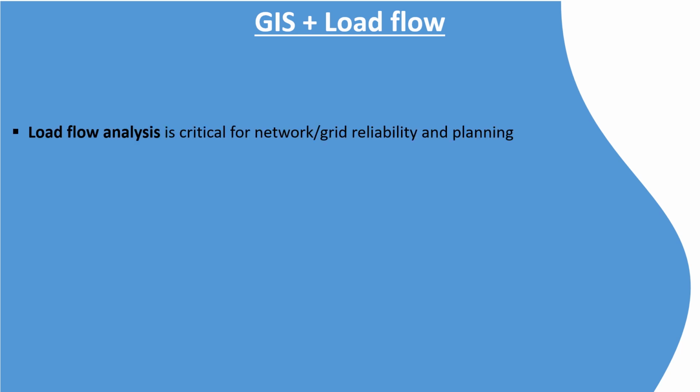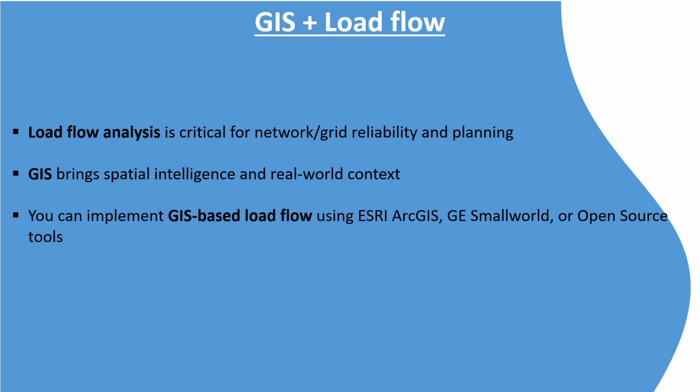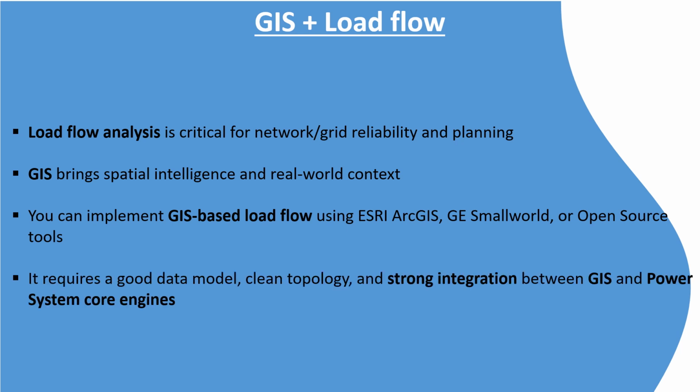GIS plus load flow. Load flow analysis is crucial for network grid reliability and planning. GIS brings spatial intelligence and real-world context. You can implement a GIS-based load flow using Esri, ArcGIS, Smallworld, or any open source tools for GIS visualization. It requires a good data model, clean topology, and a strong integration between GIS and power system core engines.